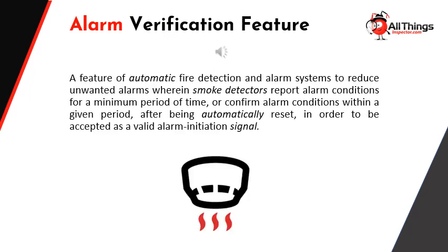Alarm verification feature. A feature of automatic fire detection and alarm systems to reduce unwanted alarms, wherein smoke detectors report alarm conditions for a minimum period of time, or confirm alarm conditions within a given period after being automatically reset in order to be accepted as a valid alarm initiation signal.